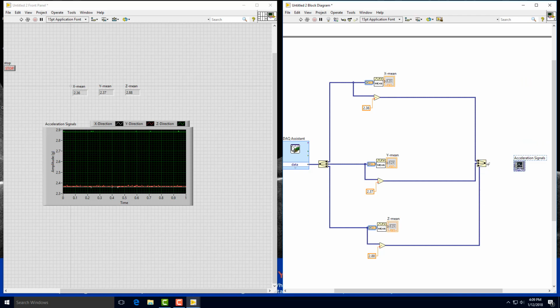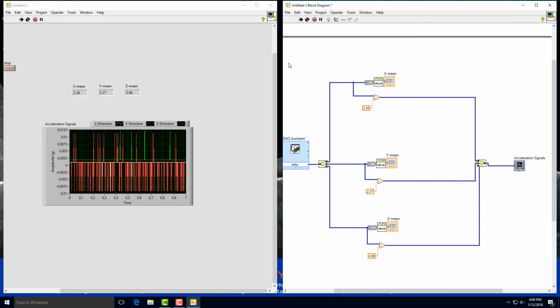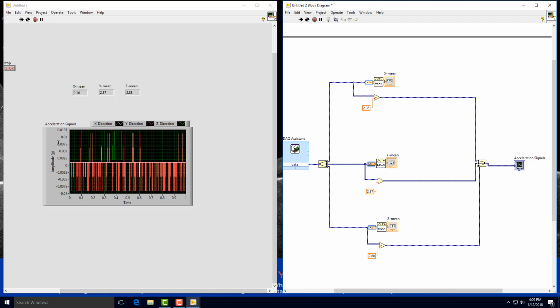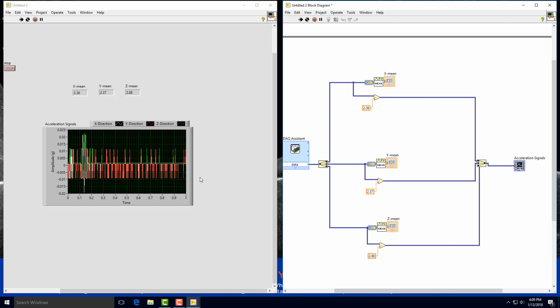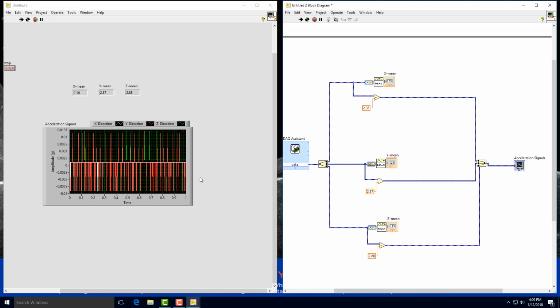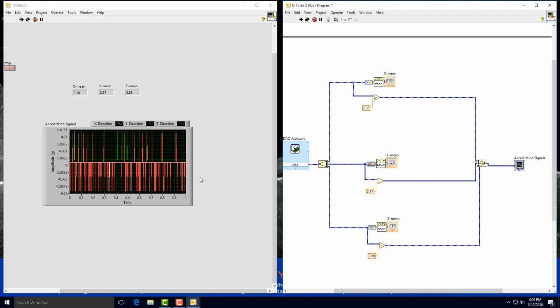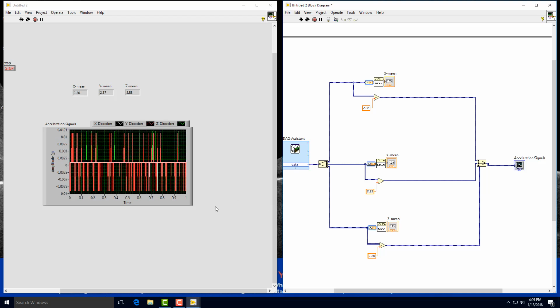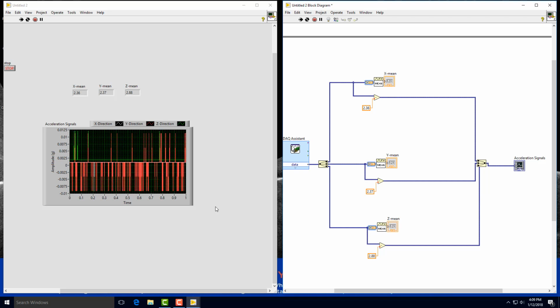If I were to connect this one here and press play, you'll see that your signal is going to be very close to 0. You'll see these peaks here because if you look at our scale, it is 0.01 and minus 0.01. So there's some fluctuation depending on the noise from the DAC card. You already knew that we will have some noise because we measured without any accelerometers last week, and you've seen some signal.